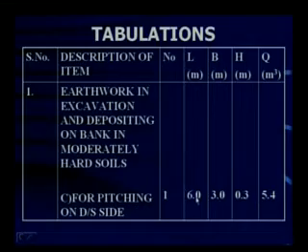Now, there is one more area where excavation is required. It is under the pipe, is it not? Before you fix the pipe in position, you have to make an excavation under the pipe to a certain depth so that it is filled with granular material and the pipe doesn't move out of place. We move on to the next topic.